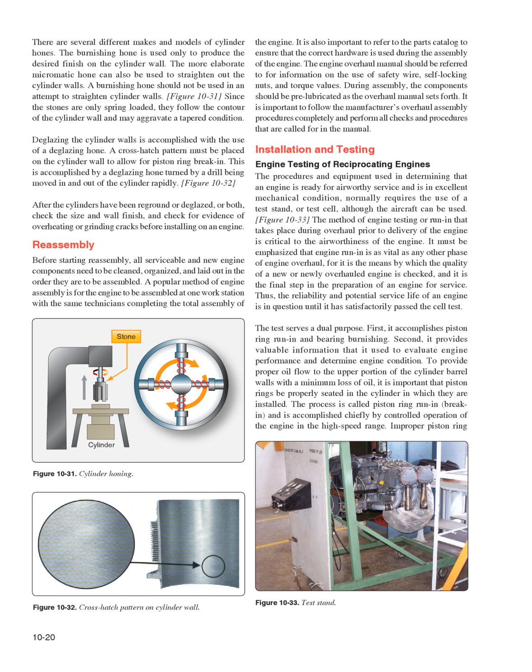Engine testing of reciprocating engines. The procedures and equipment used in determining that an engine is ready for airworthy service, and is in excellent mechanical condition, normally requires the use of a test stand, or test cell, although the aircraft can be used. Figure 10-33: the method of engine testing or run-in that takes place during overhaul prior to delivery of the engine is critical to the airworthiness of the engine.